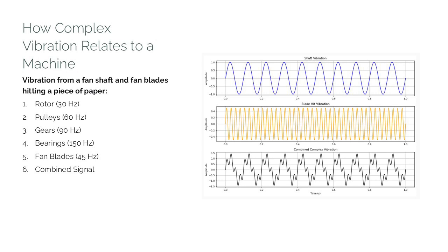Key insight we can take: if you only had the combined waveform, it would be very difficult to tell that it came from a shaft and fan blades without knowing the system. This is why frequency analysis, like FFT, is essential in vibration diagnostics.